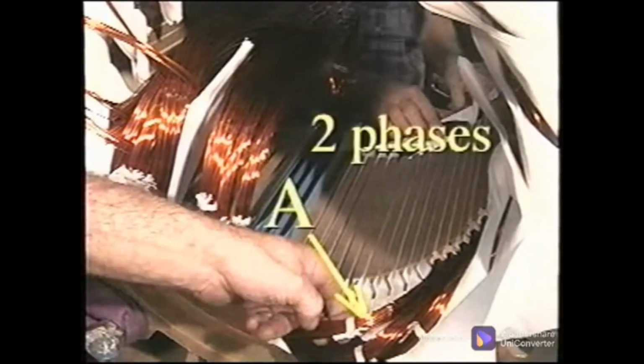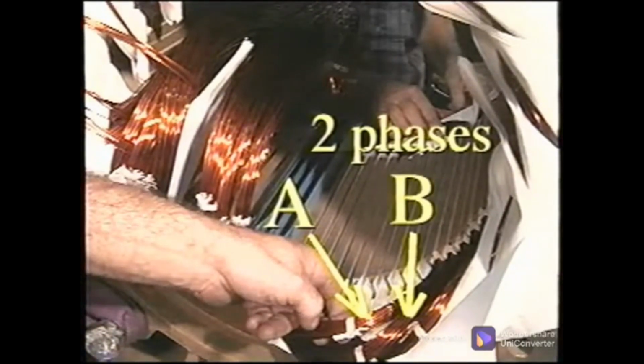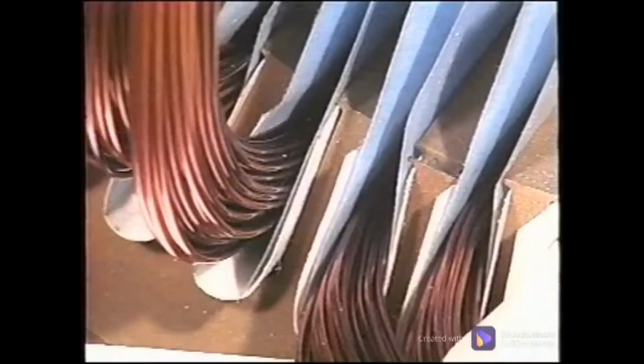Recall that in each stator slot there are 2 coils, and in a 3-phase motor the coils are from different phase legs. So if the insulation breaks down between the windings, it could short from one phase to another, which reduces the total flux and therefore the motor's power. Insulation breakdown may cause a short from phase to ground, causing flux losses.